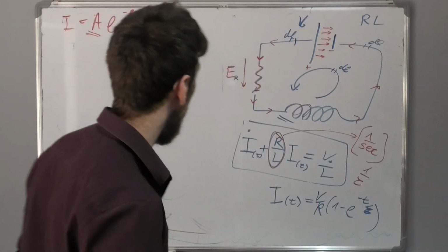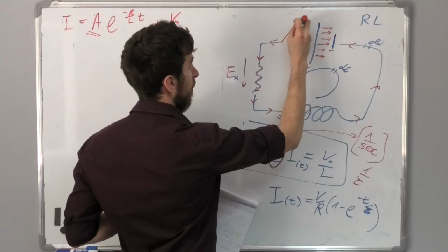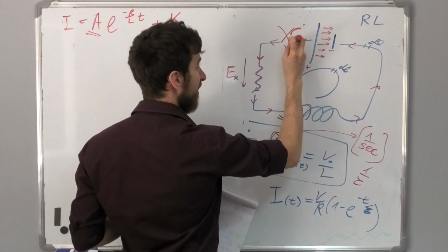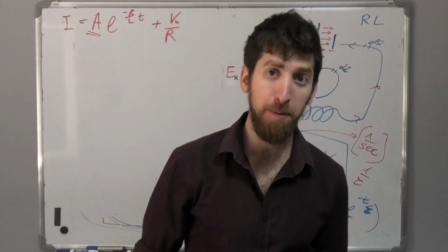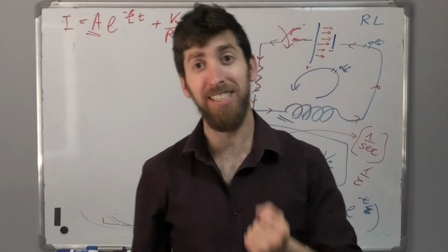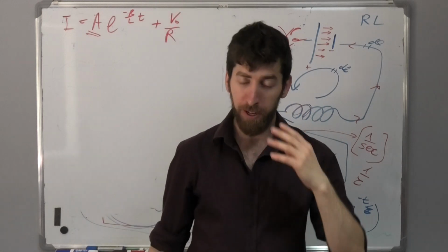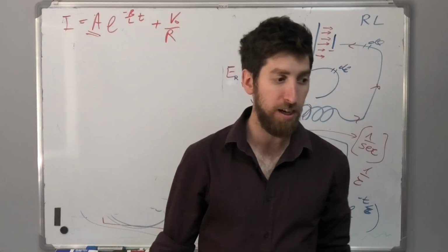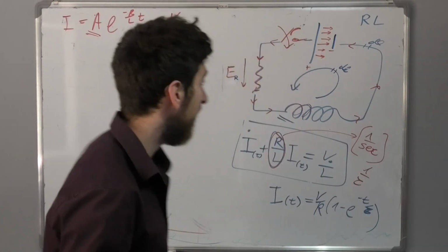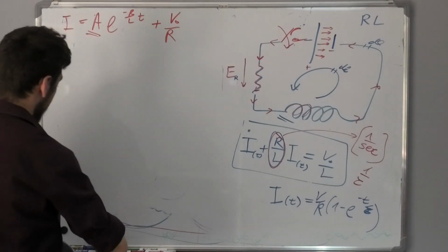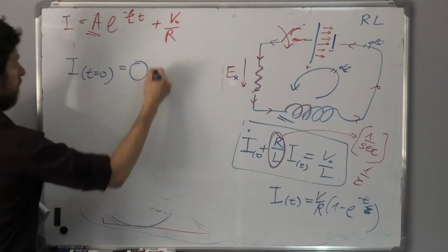until it's happening. So before I actually put the battery on, let's say that I have some knob here, and I put the circuit on. What was the current inside the inductor? It was 0. And at the beginning, time 0, the current in the circuit was 0 because the inductor would not want any change to happen. He needs to wake up, clean his face, put some water on his face, brush his teeth, take the time slowly until he's awake. So I can confidently say that at time t equals 0, the current was also 0